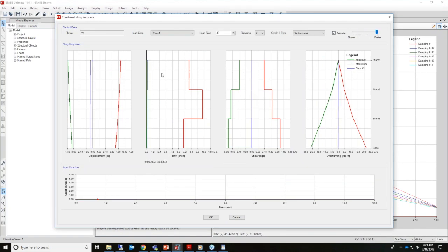And you can see over time, what this is showing you is animated plots showing story acceleration, drifts, shears, all on the same plot. So this is kind of a useful tool to take a look at. In this case, displacement, absolute acceleration can be viewed in the different directions, as well as this is the load step that's being shown simultaneously for this time history function.